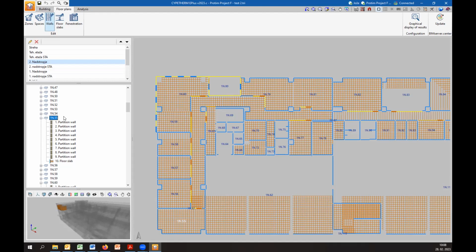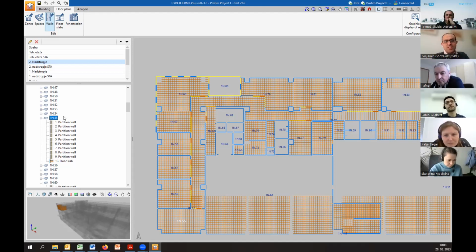Yeah, but sorry, Pablo, I think the best way for the thermal behavior of this building, this column that you have, if I were you, I think the best option maybe is if you create these walls that you're creating in the column, they have to be adiabatic walls, because you can take into account afterwards the thermal bridge with the column in the calculation, in the analytical model, in the analysis.